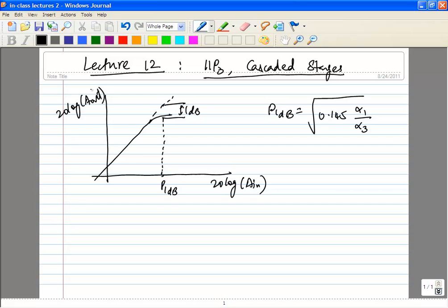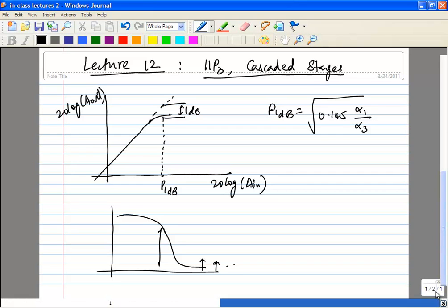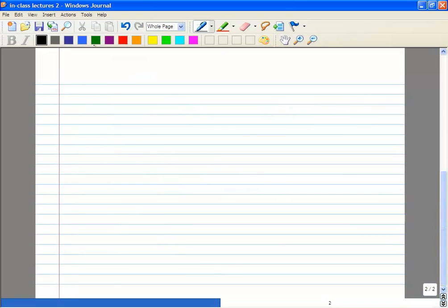And especially we saw filters, right? We saw the case why this thing doesn't work all the time, because you could have intermodulation products. So if you have a filter, the in-band intermodulation products, you'd be able to see them, but the out-of-band intermodulation products would look artificially good. So that's why you need something called IIP3.